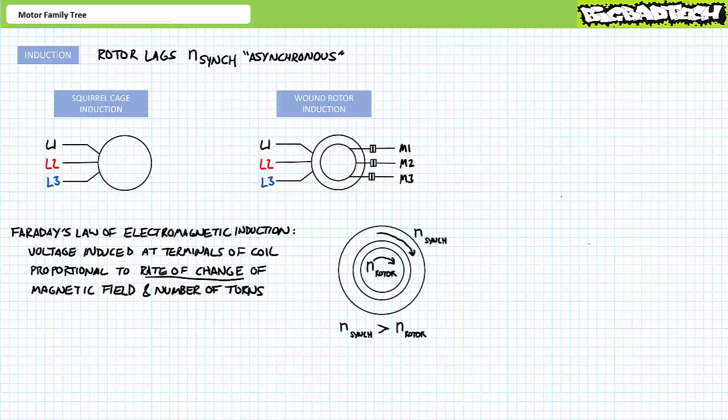Faraday's law of induction applied to induction motors means current flowing in the stator windings creates a rotating magnetic field. The rotor experiences a changing magnetic field, and via induction, a voltage differential occurs and thus current flows on the rotor. Consequently, the induced current flowing in the rotor creates its own magnetic field on the rotor, which then interacts with the stator rotating magnetic field such that the rotor is twisted or dragged along with it. Key to this interaction between magnetism, electricity, and movement is the important qualifier, changing magnetism. Induction doesn't happen if the magnetic field isn't changing.